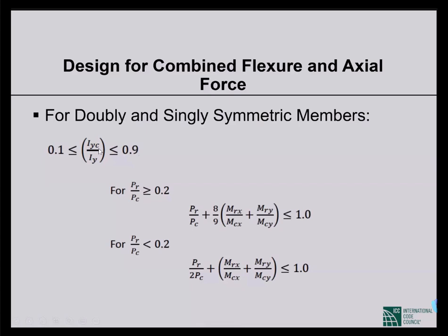So it always satisfies most of the time. If it satisfies, then if the required strength is more than 20% of the available capacity, then we have this expression which has got a factor 8 by 9, and if it is only 20%, then the expression is a little bit different.